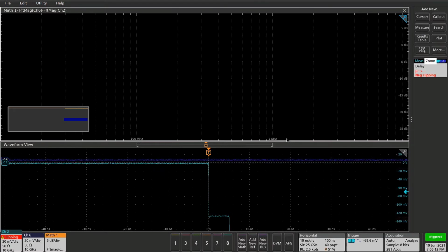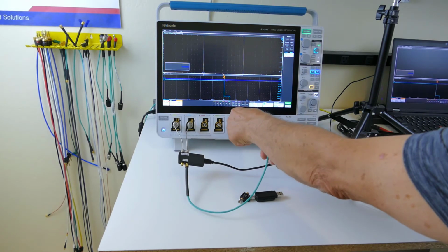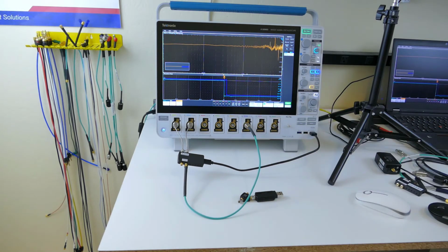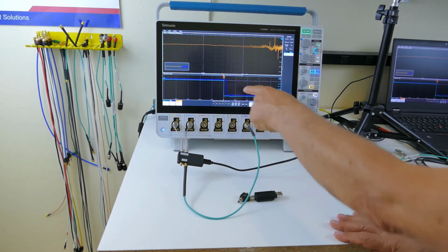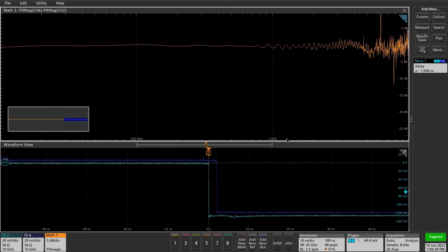We're also going to need to connect this at the other end to our oscilloscope. So we're going to use a second channel here. And now you can see my two channels on the oscilloscope. Now, how do we measure bandwidth? Well, the way we're measuring bandwidth is we're taking the differential of this edge. It's a really fast edge. But we take the derivative of that, and then we do the FFT of the derivative.